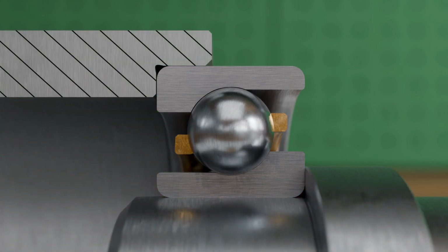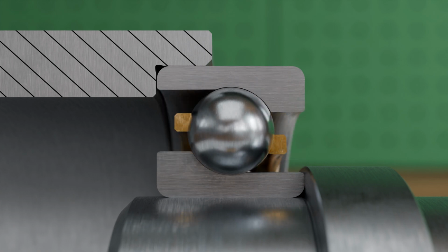The bearing must be installed in the shown situation so that the inclined raceway of the inner ring faces the shaft shoulder. The raceway of the outer ring must be aligned accordingly with the housing shoulder. In this way, the shaft can transmit a force to the left onto the inner ring, which transfers it via the rolling elements to the outer ring. The load is then directed from the housing shoulder into the housing. If the bearing were installed rotated by 180 degrees, there would be a risk that the inner ring could be pushed out of the bearing under high load.